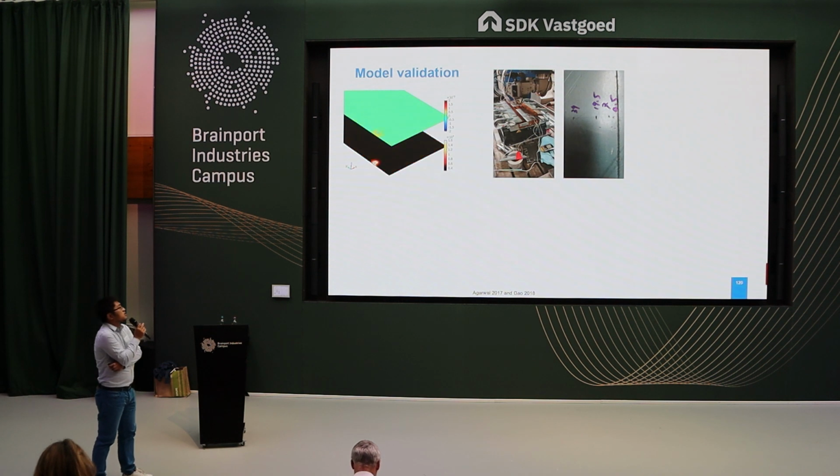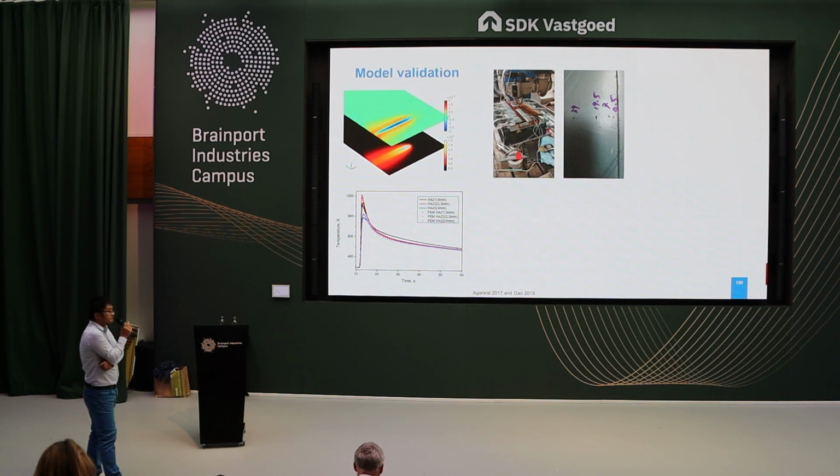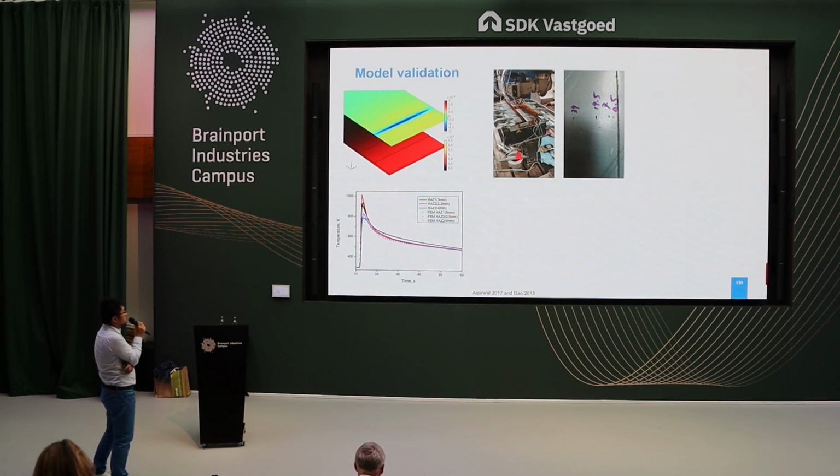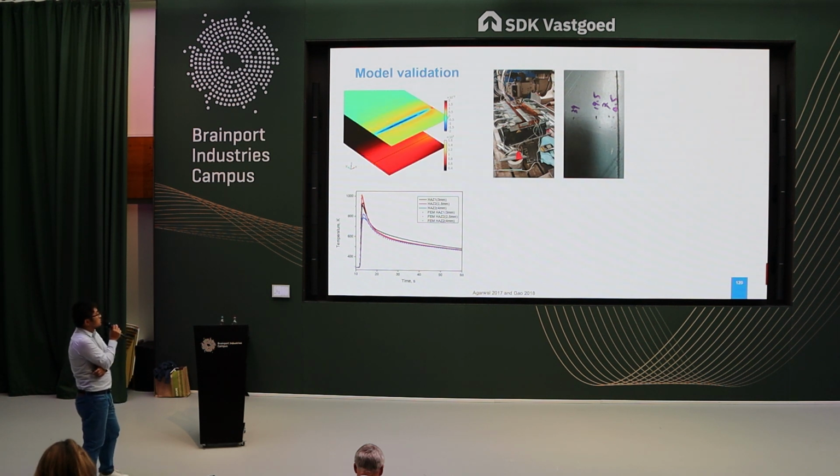So for the thermal part, we use some thermocouples to measure the in-situ temperature during welding, and then after welding, we measure the location of the thermocouples. Then we extract the predicted time-temperature profile at the same locations. I have to say that I'm quite satisfied with this validation: not only the peak temperature, but also the temperature profile in the heating and cooling stages closely resembles the measurement.